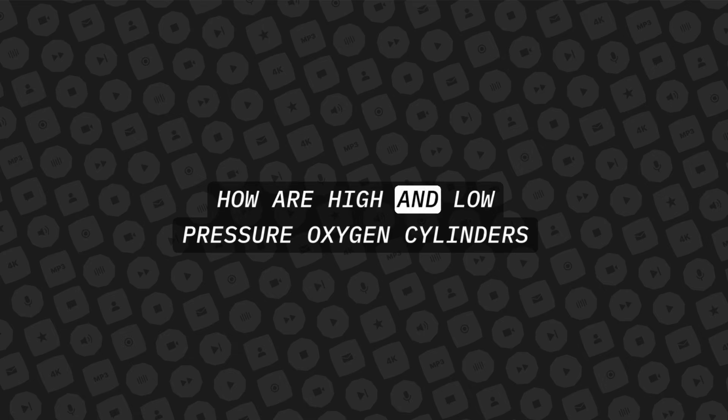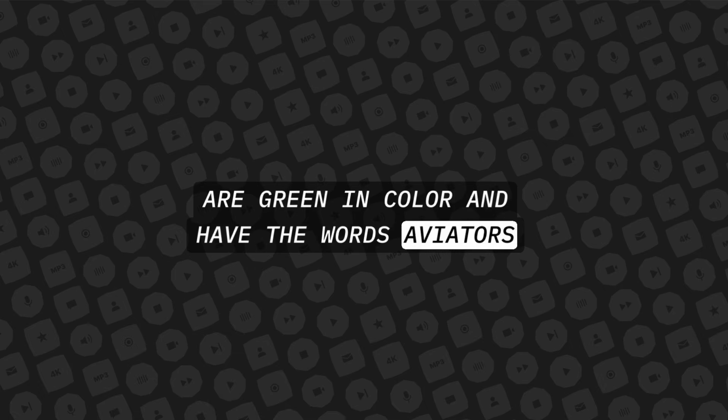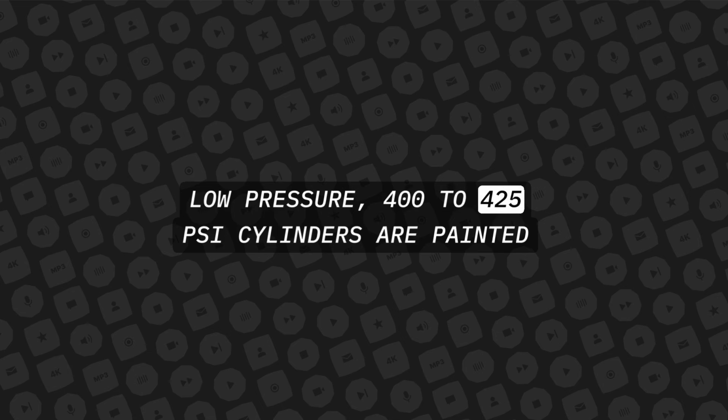How are high and low pressure oxygen cylinders identified? High pressure, 1,800 to 1,850 psi, oxygen cylinders are green in color and have the words Aviators Breathing Oxygen stenciled lengthwise in white 1-inch letters. Low pressure, 400 to 425 psi cylinders are painted light yellow.